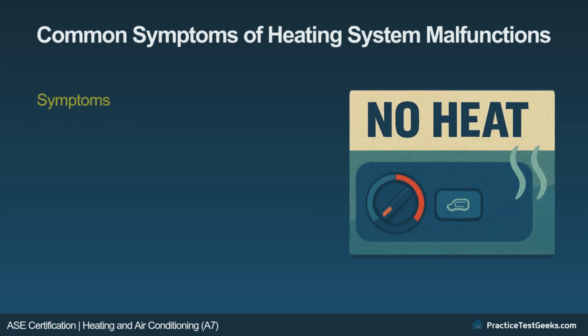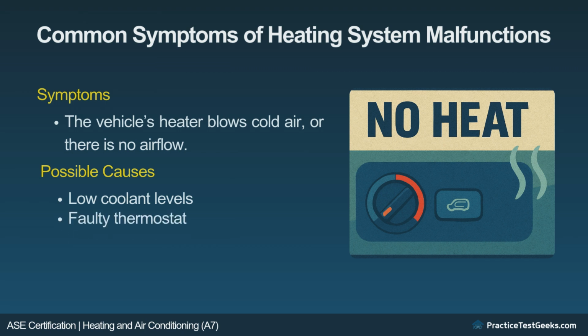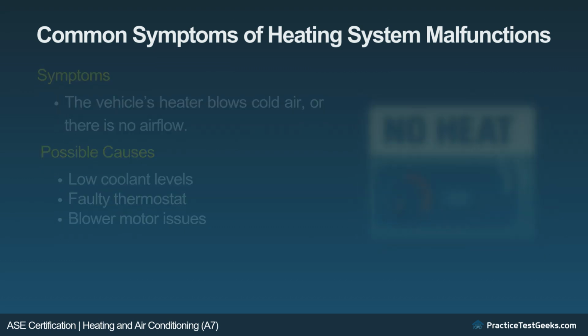No heat. Symptoms. The vehicle's heater blows cold air or there is no airflow. Possible causes. Low coolant levels. Insufficient coolant prevents the heater core from transferring heat. Faulty thermostat. If the thermostat is stuck open, the engine may not reach the proper operating temperature, preventing the heating system from working. Blower motor issues. If the blower motor is malfunctioning, there may be no airflow through the heating system.